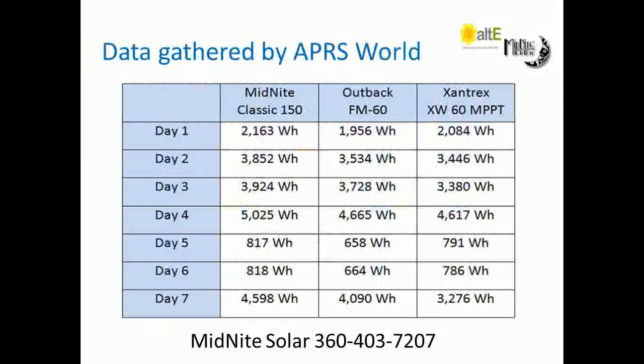Some of the things we get asked a lot about charge controllers is, what's its efficiency? Well, you could have a piece of electronic gear that's 100% efficient, and if your tracking algorithm is not very good, the efficiency of the hardware makes no difference at all. It's like having a 1,000 horsepower engine under the hood of your car, but your automatic transmission doesn't have any clutches in it, so it's not hooked to the rear end.